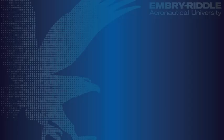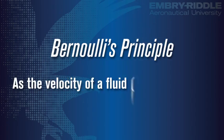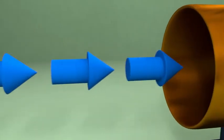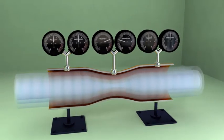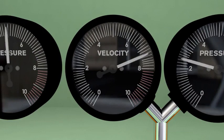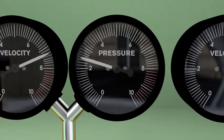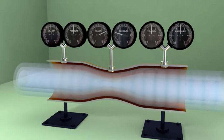The other main theory of lift is Bernoulli's principle. This principle states, as the velocity of a fluid, in this case air, increases, its internal pressure decreases. We can visualize this by having air flow through a tube with a narrower middle section, which we will call a venturi. As air enters the tube, it is traveling at a known velocity and pressure. When it arrives at the narrower portion, the velocity increases to allow all of the air through. As the air's velocity increases, the air's pressure decreases. Then, as the air exits the narrower portion, it returns back to its original velocity and pressure.